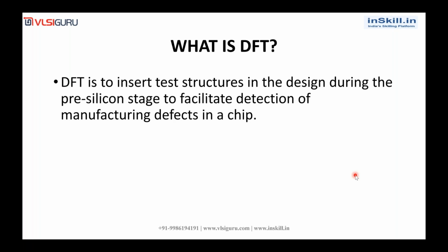So DFT is to insert test structures in the design during the pre-silicon stage, that is before manufacturing, to facilitate detection of manufacturing defects in the chip. So if a particular chip fails after manufacturing, the DFT team will be able to tell what manufacturing defect has caused the chip to fail.